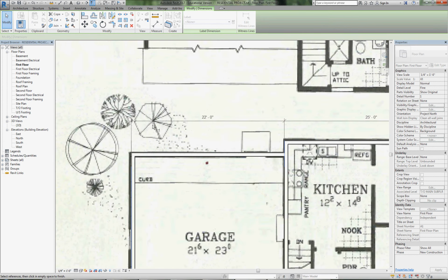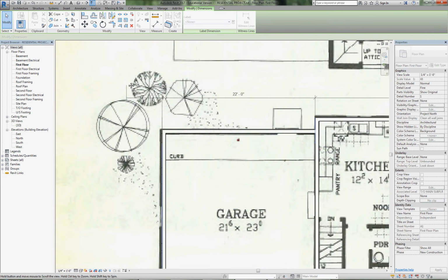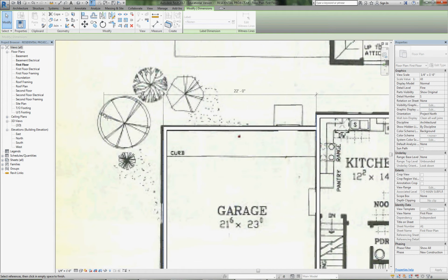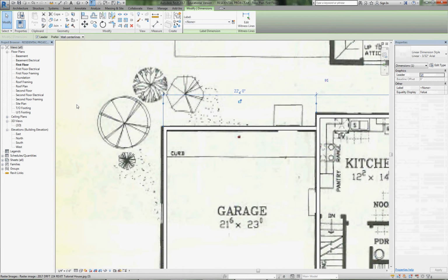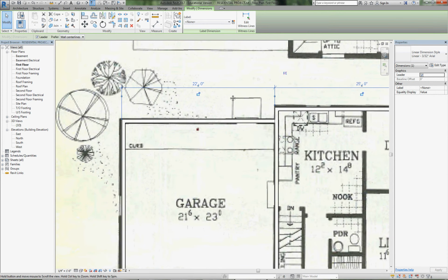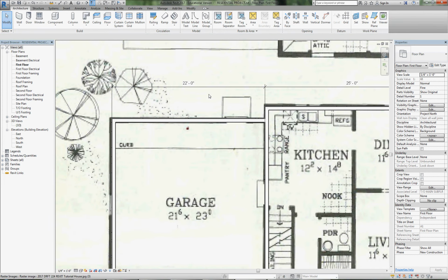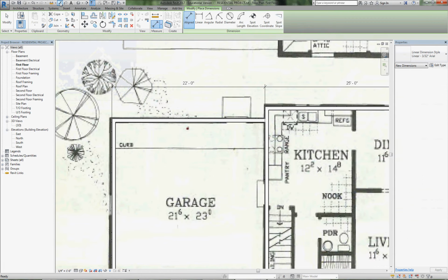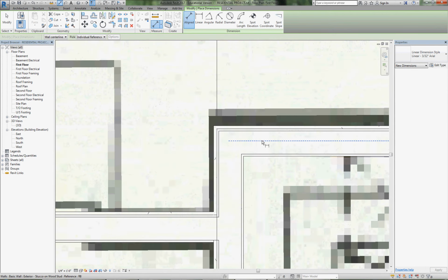Now I've got the length of this done, but in this command it expects that we're going to keep on adding dimensions. If you hit enter now, you'll just lose the dimensions. So you have to go somewhere where there's nothing to attach to and just click there. That will terminate the extension command, and now we've got those 2 walls connected with a dimension. I'm up to my quick toolbar here, and I'm going to click on align dimensions. Now I'm going to do the vertical dimensions.